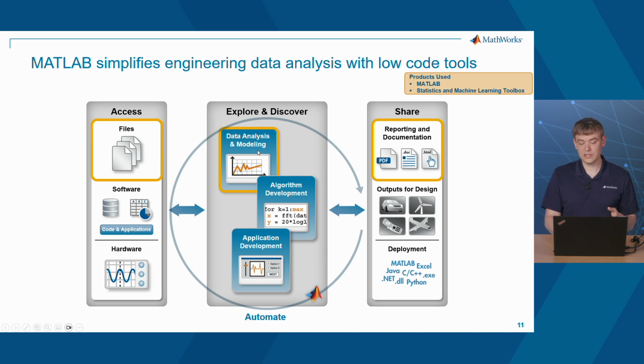So in today's demonstration, we looked at how MATLAB simplifies engineering data analysis with low-code tools. We looked at importing data from an Excel file. We did some basic visualization and analysis and trained a machine learning model. And we looked at one simple way of generating a report. If you're curious, along the way, the products we used, almost everything was done with the base MATLAB product. The one exception is the Regression Learner app, which came from the Statistics and Machine Learning Toolbox.